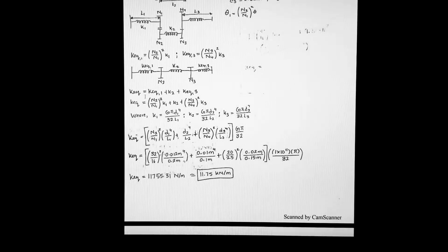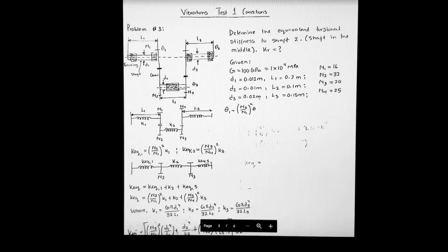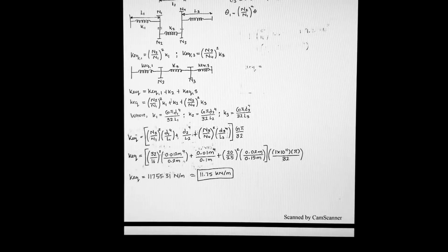Then making this solve for the total spring equivalent constant at K1 and K2 and K3, and then solving for what each part is, which is N2 and N1, which are given right here. We have all this set up, and we actually calculated the K equivalence, plugging our givens into the equation, then we get 11.57 kilonewtons per meter.